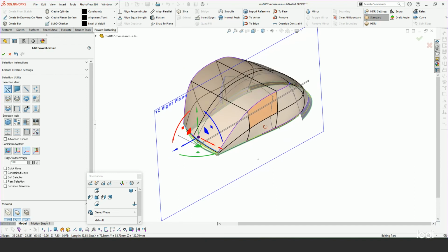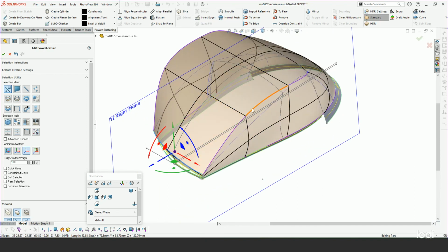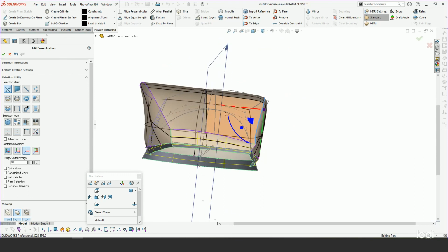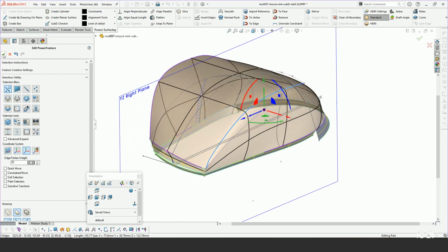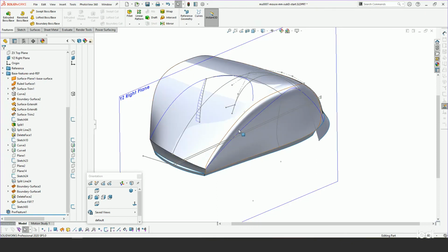One other thing I need to explain is, when I made these edges hard, we could have actually put a radius there by just softening the edge or putting less weighting into that edge. And if we want to turn that down, actually put a fillet in there, we can do that. The reason I didn't do that is if we just rebuild and show it, that edge right there, which is part of the sub-D, will not show because the minimum radius of curvature is less than what you can show. So generally, when I work in sub-D, I don't try to make radiuses or small radiuses in sub-D for that very reason. I think that's an important thing to point out if you're looking to really try to do that with your sub-D surfaces.